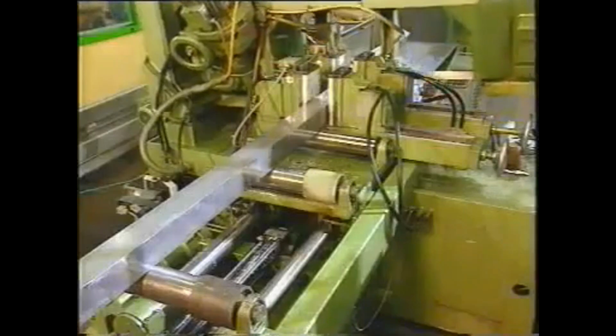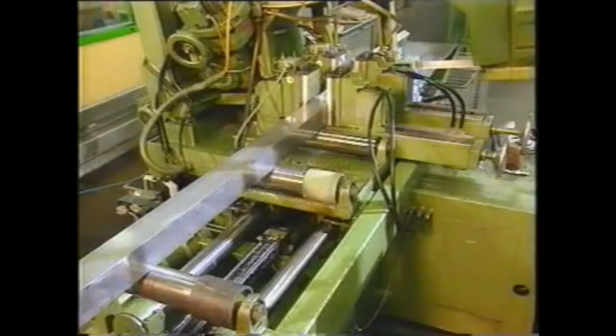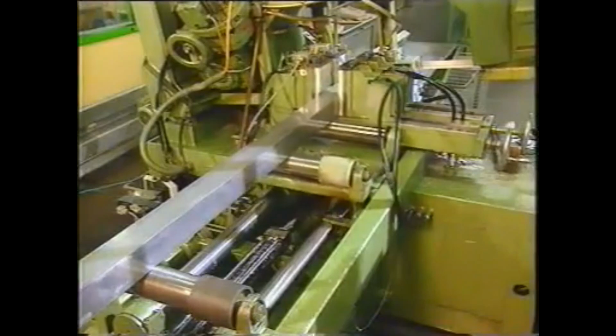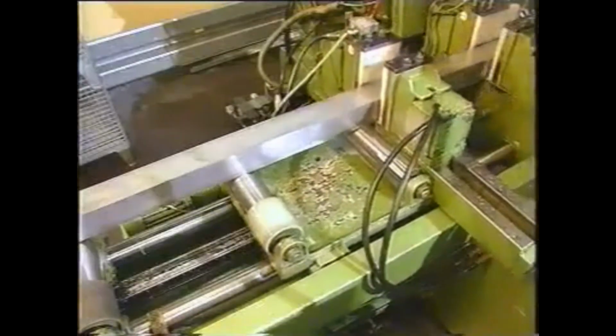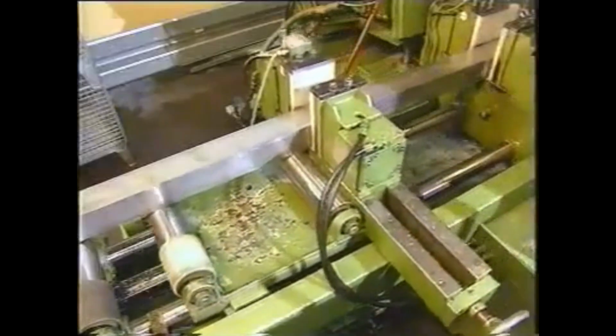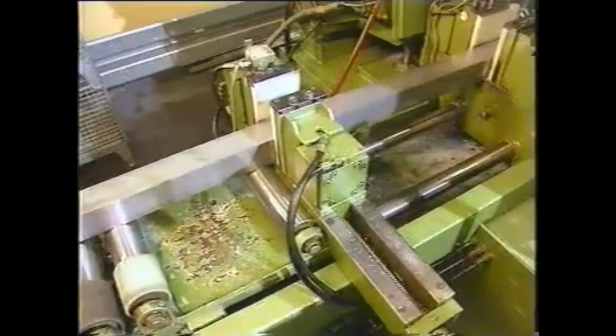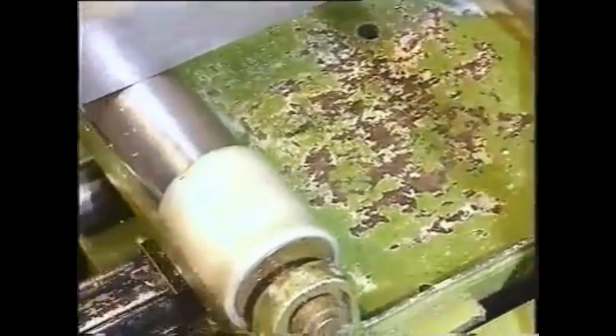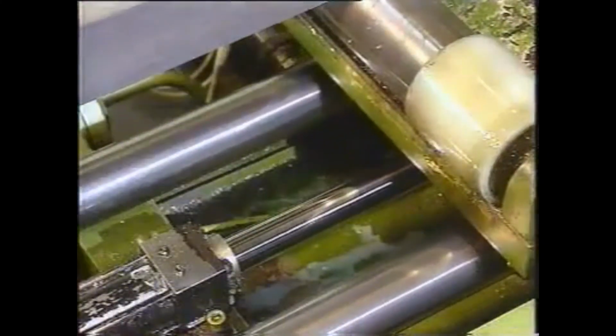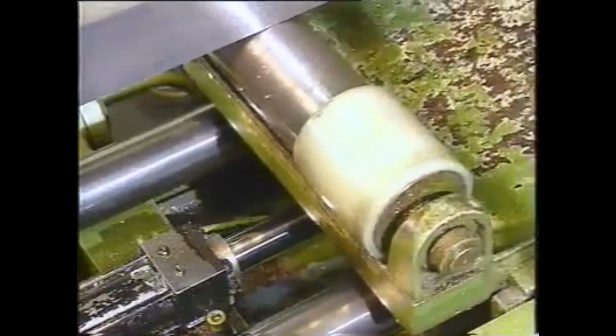Just one more word about pressure conditions in hydraulic systems. We have two basic situations. First, there is the dynamic situation. Here, for example, the highest pressure set at the pressure relief valve cannot be used as transmission or working pressure to move a load. The reason is that when the oil flows through valves and pipelines, there could be a loss of pressure. The loss can be as high as 25%.